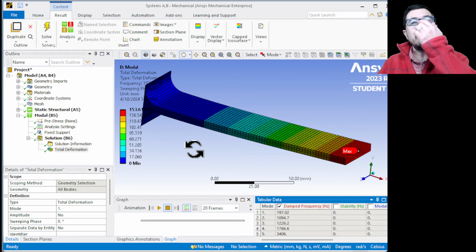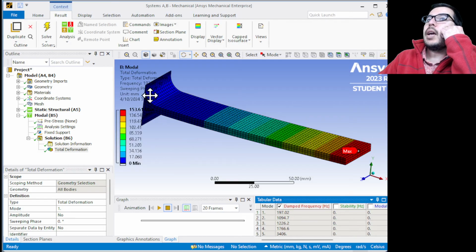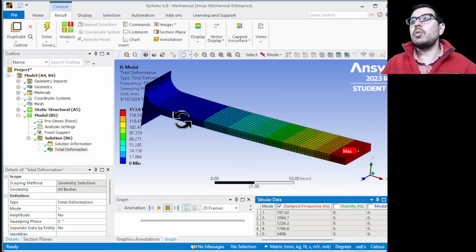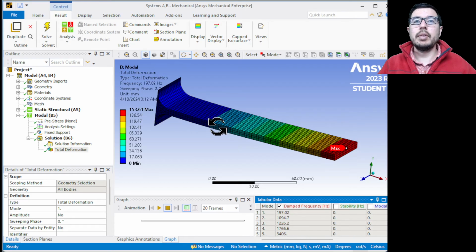And also we should note that we added this amount of mass at the end, and we got rid of the stress concentration, but in a sense we've created a slightly shorter beam, and a beam that also has a slightly larger cross section, at least in this region. So that means that the resonant frequency that we have is going to go up.